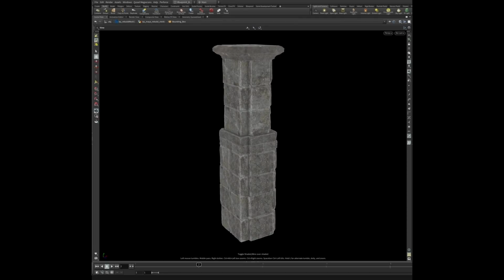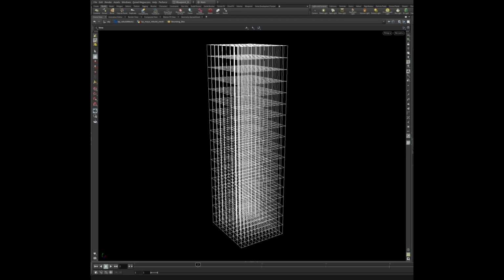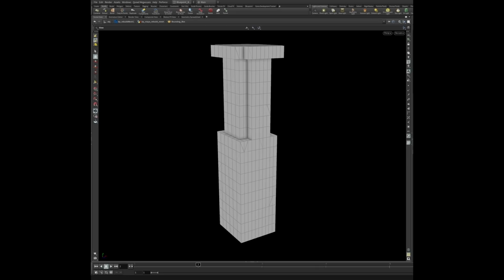So I'm going to do a quick rundown of that collision generation process. It looks really awesome, but it was really simple to set up. Basically, you take in your original geometry and VDB it, which gets rid of all the stuff in the middle, and then I convert it back into polygons after the VDB. In another node, I generate a bounding box and fill it with a grid full of points, and the artist can determine the actual grid size that they want. Then I have a quick VEX wrangle to snap all of the points to the nearest point on the grid.